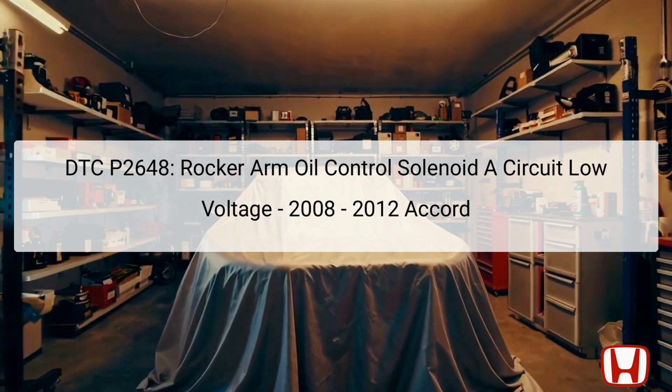The rocker arm oil control solenoid is responsible for regulating oil flow to the rocker arms, allowing the engine to adjust valve timing. When a low voltage is detected in this circuit, it signifies a potential issue with voltage supply or electrical integrity in the solenoid circuit. The fault can lead to decreased engine performance and increased emissions, making it essential to diagnose and fix promptly. Understanding this DTC is vital for effective troubleshooting and maintaining optimal vehicle function.